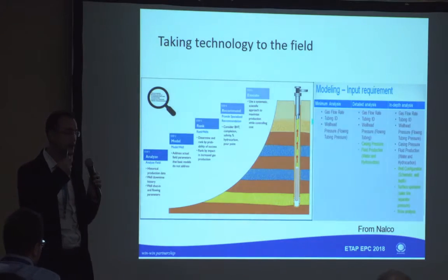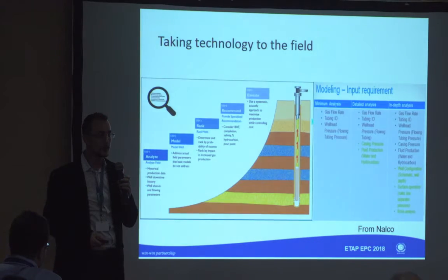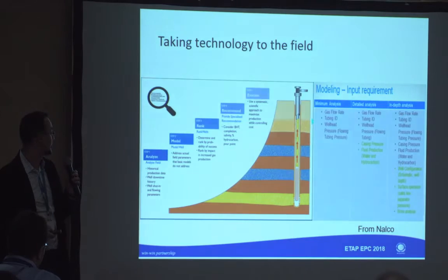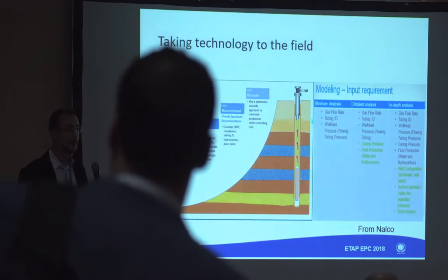You need to calculate how long you need to wait for the foamer to arrive at the bottom, based on average speeds of liquids. We also put in place a system to monitor the well production, to determine what impact the foamer was having on the production of the wells, but also on the facilities and the quality of the separation between the different phases.